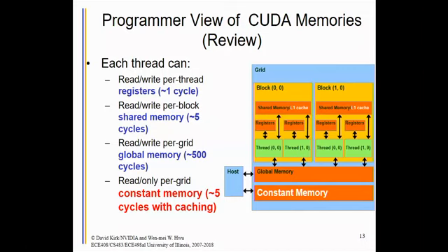But in this case, the mask is a lot smaller than the input. So if you have a small piece of hardware that automatically captures these values and puts them near the compute unit, you don't need much hardware. In that case, 25 elements will be good enough, right? So you can have a very easy mechanism to store them as cache values.